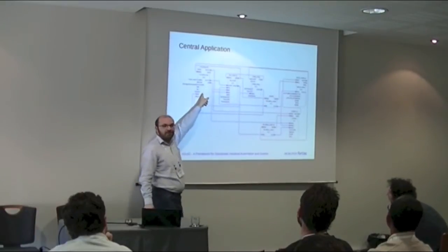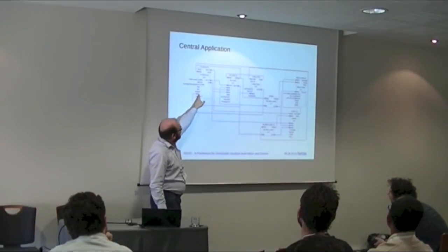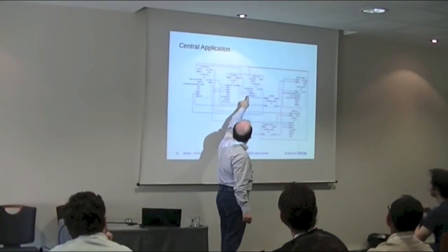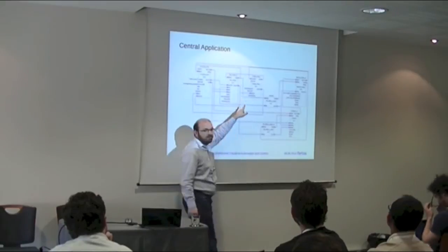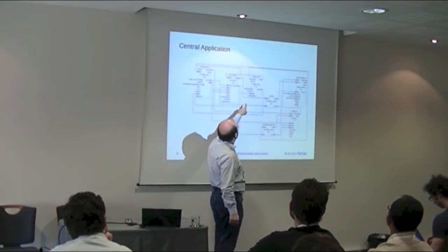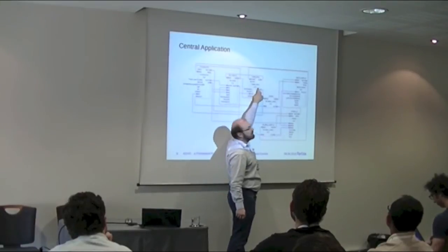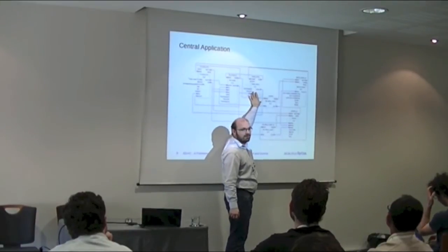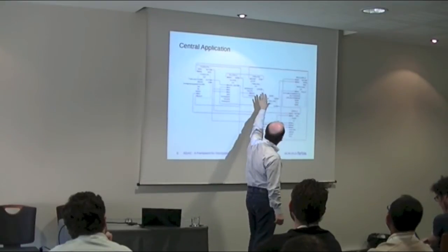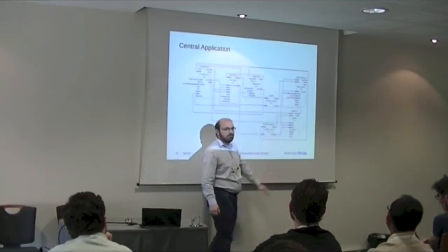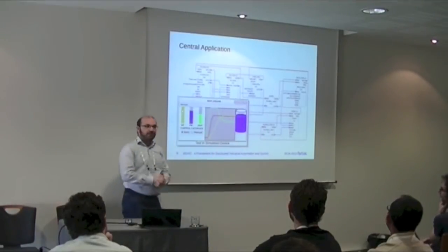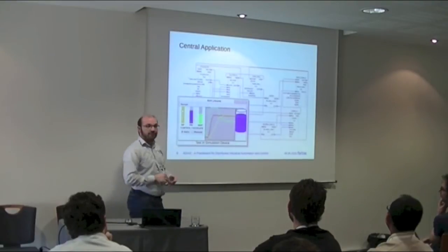It will get a set point from an HMI and tries to control the feed, the pump speed, in order to maintain a certain tank level. So this function block, called tank model, simulates our tank. Here we have some view that will show us the tank afterwards. Here we have a function block that will present us a strip chart, but it's easier if I show it like that. And if you run this in my simulator, it will look like this.